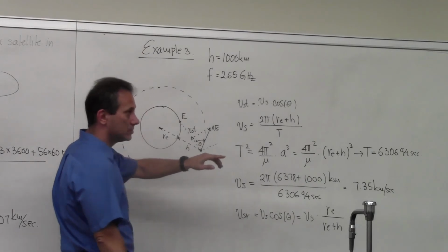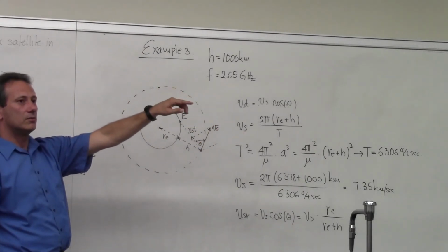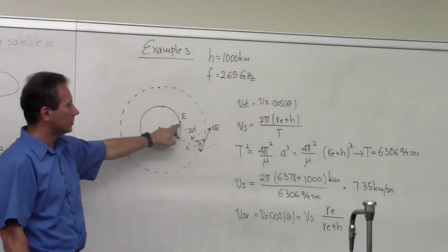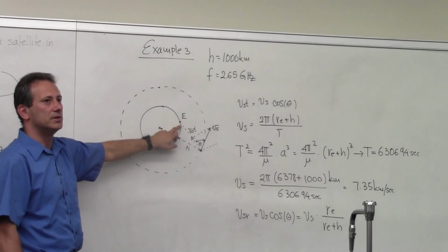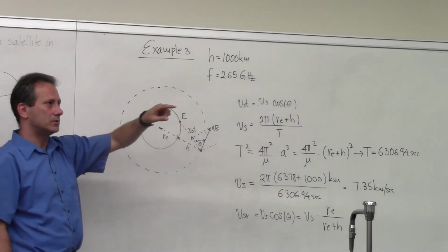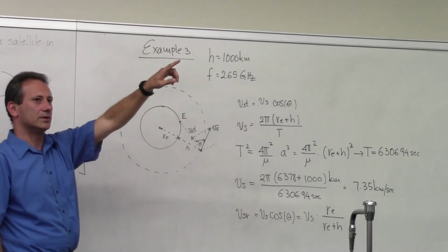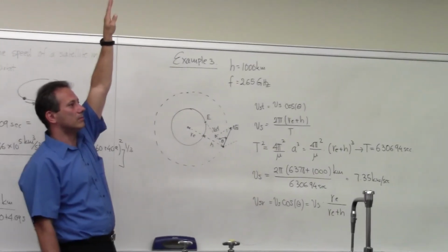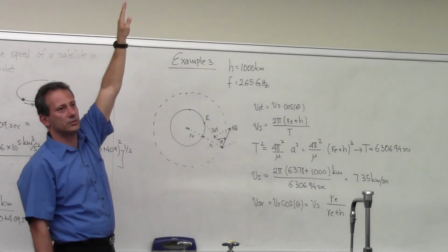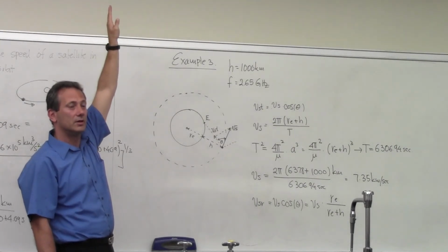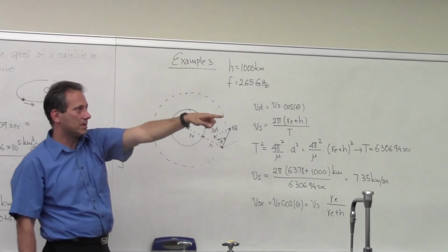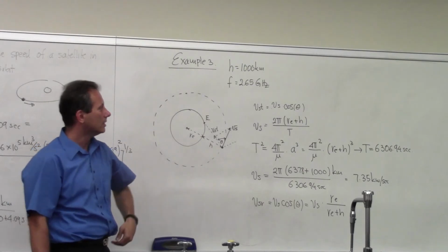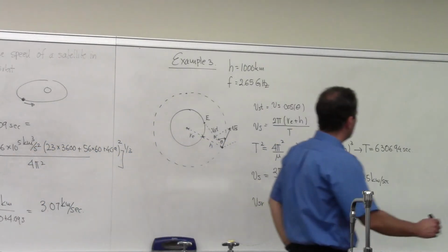When is the satellite traveling towards the point on Earth at the fastest speed? When you're just coming above the horizon, right? Because when you're up here, your velocity is tangential, so you're kind of going parallel to the Earth station. But when you're coming up over the horizon, you're actually moving straight towards, or your component towards your Earth station